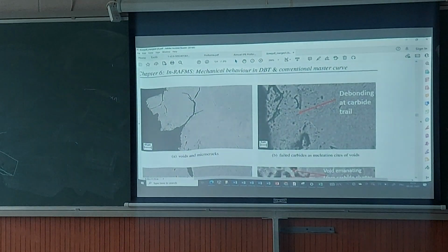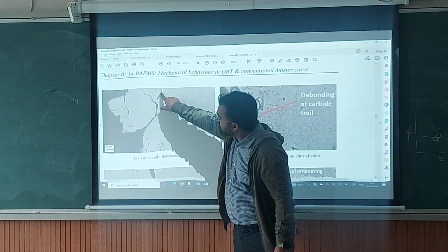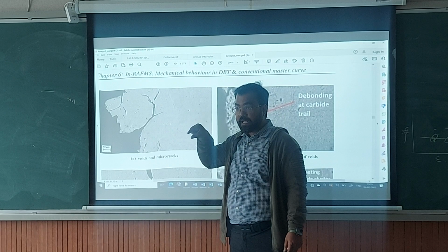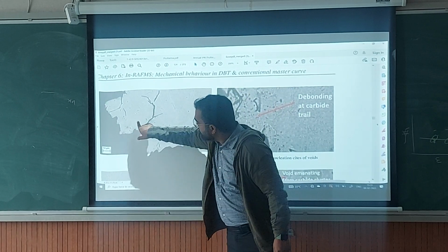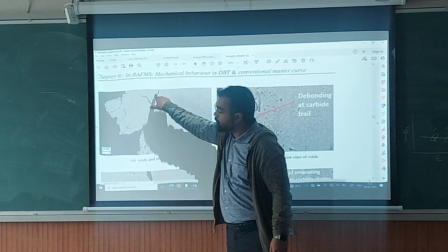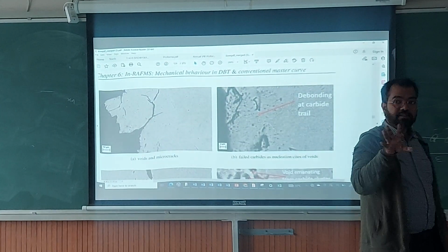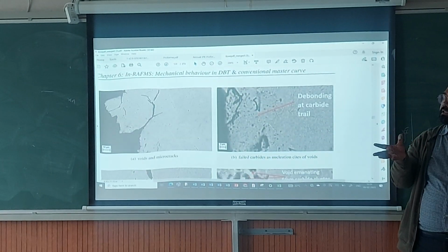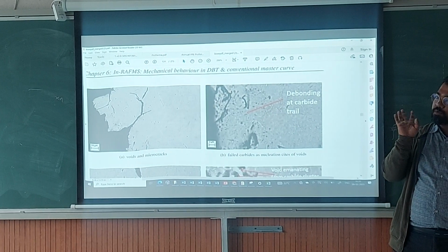So you see, this is a bigger crack which has formed because of joining of 2 small cracks. Okay, 2 small micro cracks. So you have micro crack there, there, there. These are not voids. They form from the secondary phase only. But micro cracks contributes to brittle fracture and void contributes to ductile fracture. So we'll discuss about micro cracks later.